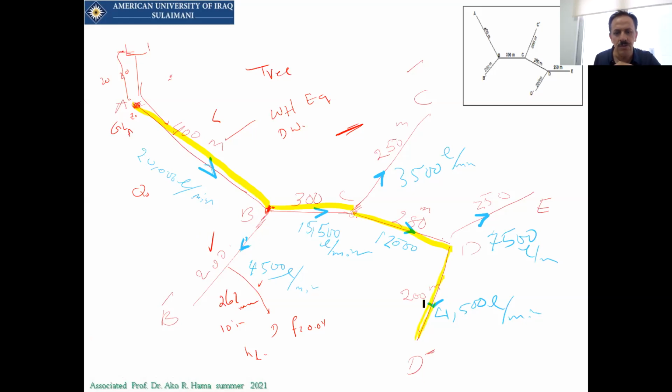So what you should do next: you can see we have different pipe diameters. Here we have 400. You just unify all these yellow highlighted lines with one diameter, and then the laterals, these are all called the laterals, will use another pipe size, and this will help minimize the head losses in the pipes.